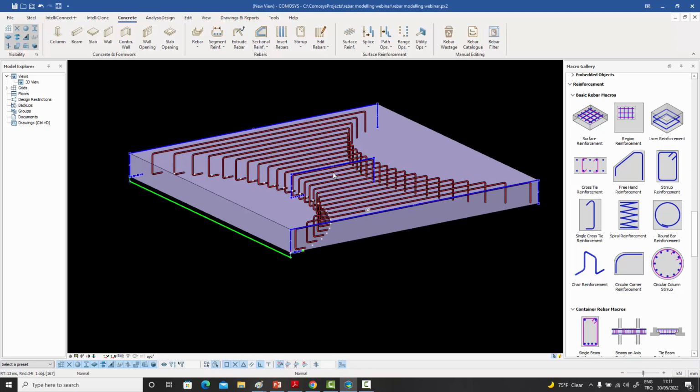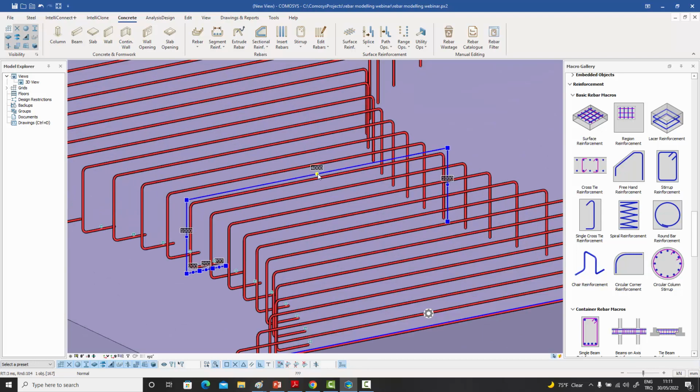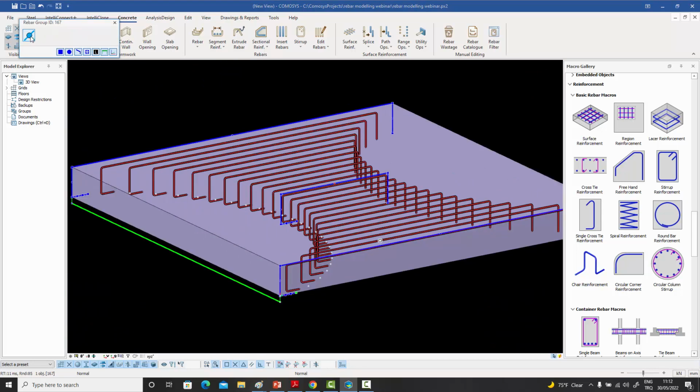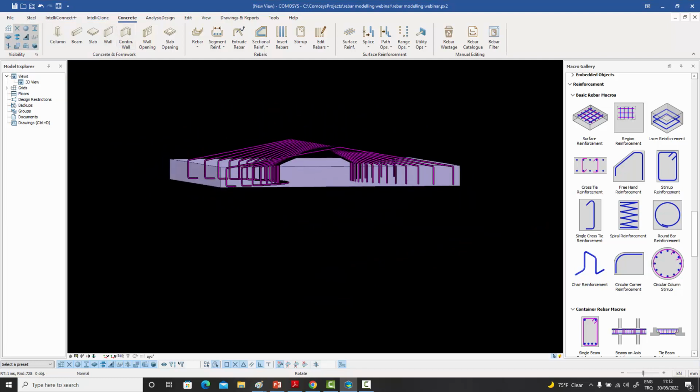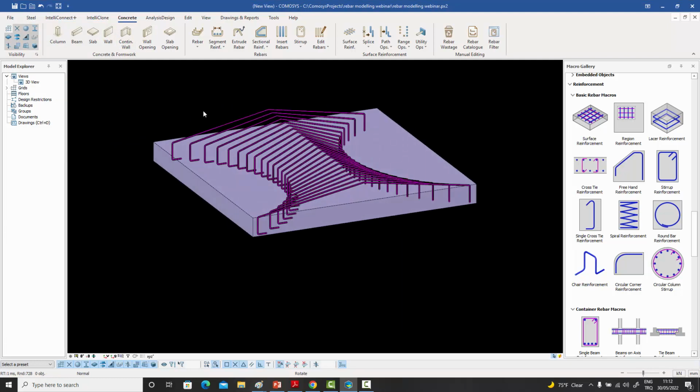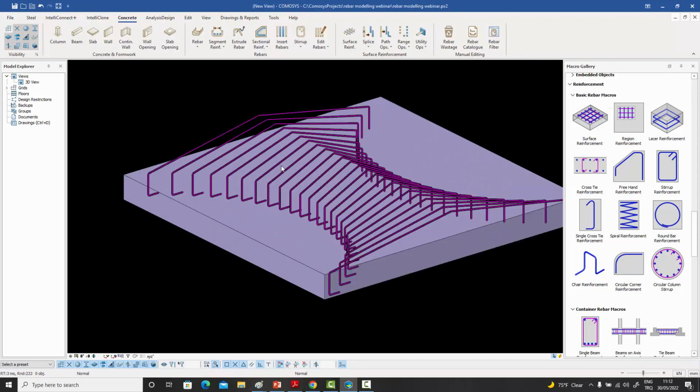You can do the same by, for example, what you could do is you could add a midpoint over here, and you can say plus, and you could give it, say, a z direction of 1000, move. And once you do that, you've inserted even more points. So you can see very clearly on the screen what's happening, and you're becoming an even more advanced user as I speak.